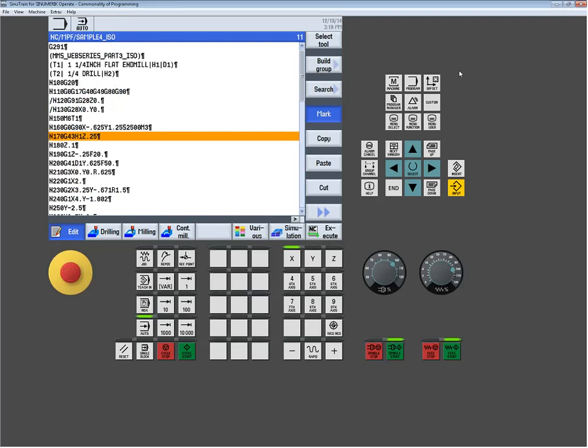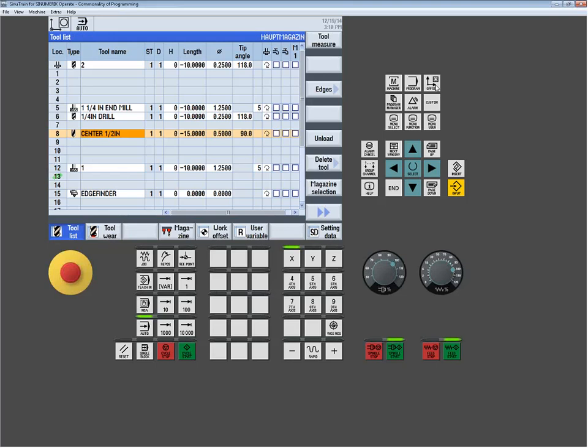Well, that is because once you get to ISO programs, you have to start using this H column. In the H column, I'm going to put the number, or the name, of the tool. So in this case, tool 2 is my drill, so I need an H tool. That H will also correlate to the D number as well. So you have the name of the tool you want to be associated with here as well as in the H column. So 1 and 1, 2 and 2. This is very important. It's the only time you ever use this column.